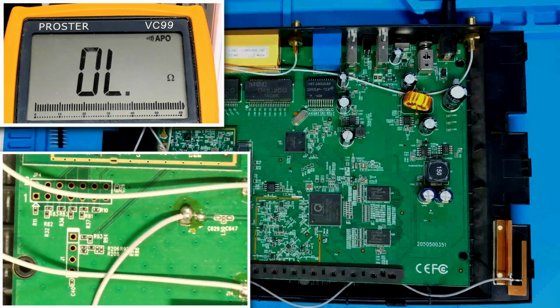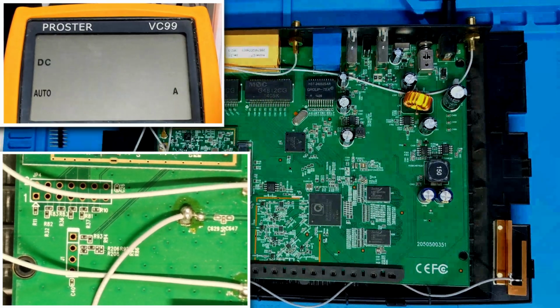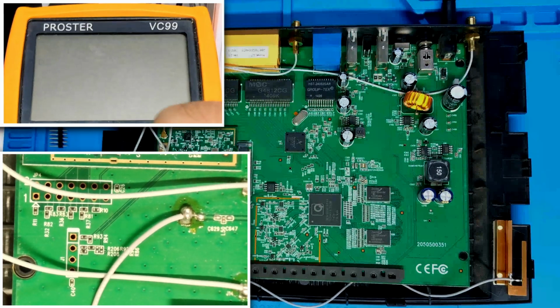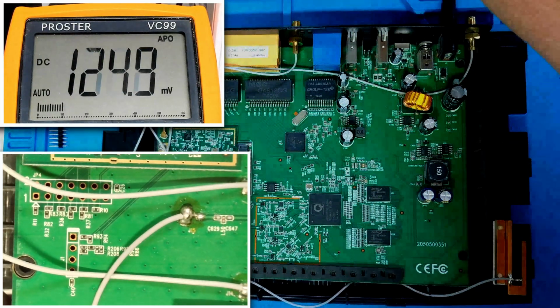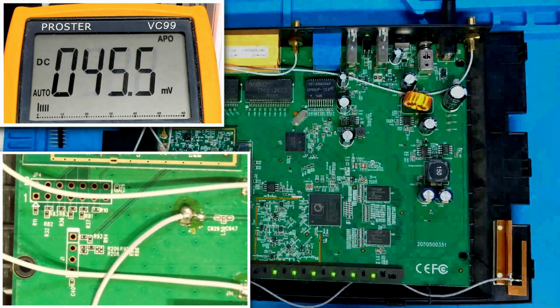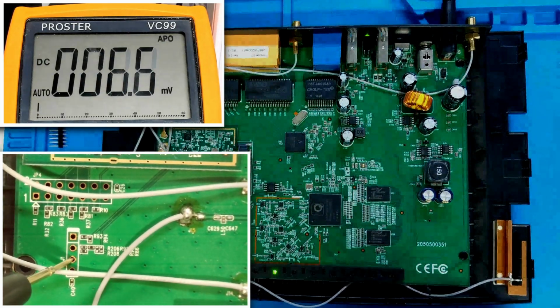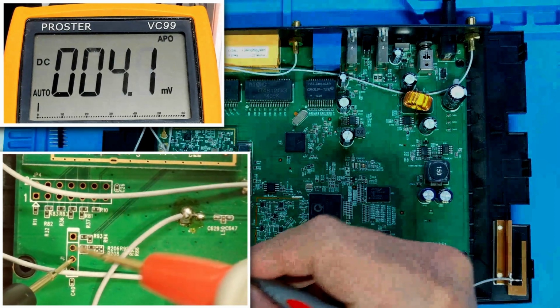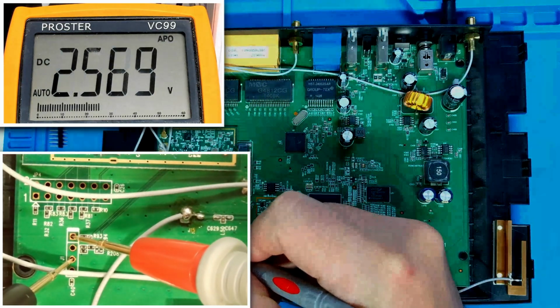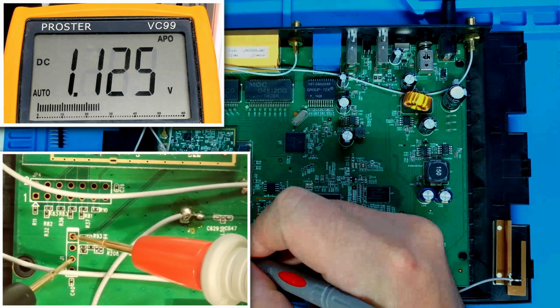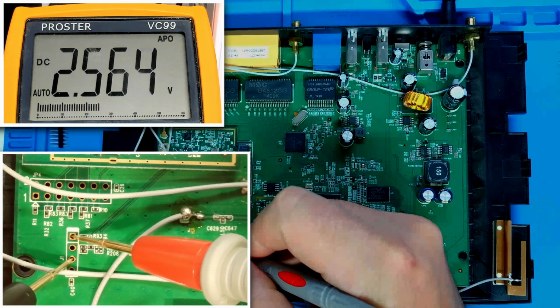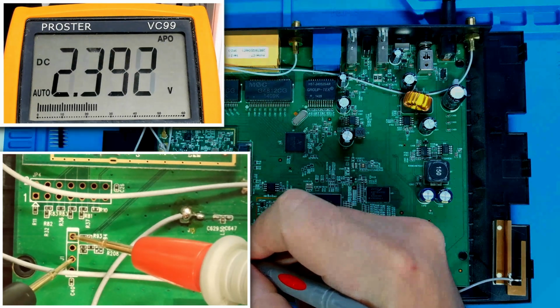So now that I've identified ground, we can switch over and look at the voltage, and we can start using that ground as a reference. I'm just going to power on the device, and referencing ground, we'll start with pin 1, and we see pin 1 is at 2.5, 2.4. It's kind of moving around. So to me, that's a pretty good candidate for TX. We can see it just moving around there.